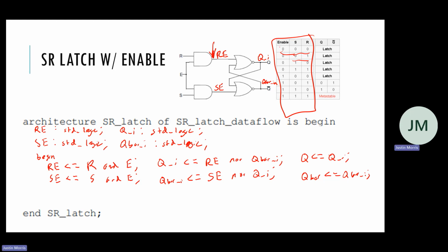If you start with the 0, 0 case, it will still just output 0 because of the AND gates with the enable. So it'll be forced to, no, it might still just show as undefined. So just don't start with 0, 0. But even then you can start with 0, 0 and make sure that it still stays undefined. Things like that. But you should just test all of these cases because there are only a few cases, right?